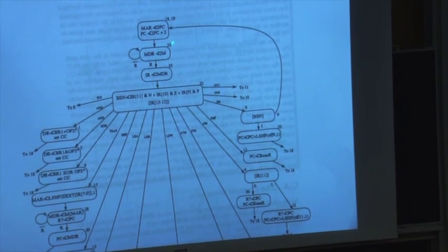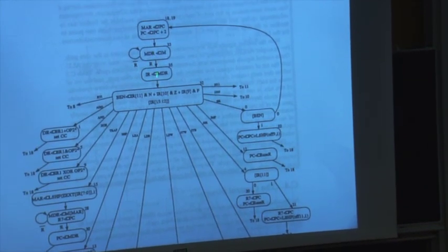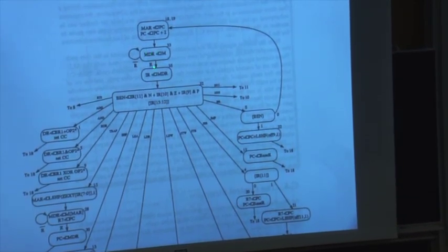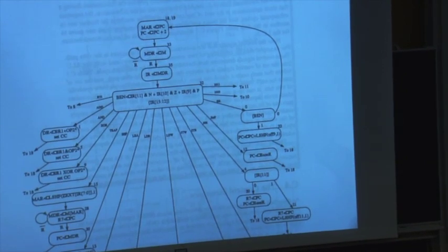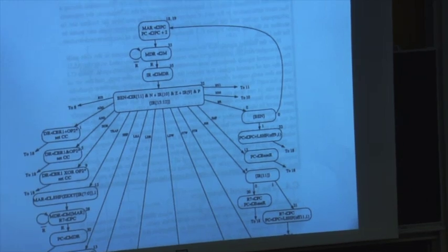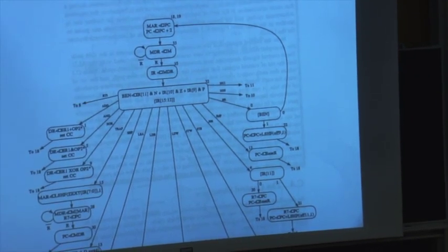Now, in the next state, state 33, the transition is conditional, right? The next state is determined by not only this current state, but also whether this R bit is set or not. Now, what is that R bit? That R bit comes from memory, and it says, is memory ready? You've already put an address into the memory, and you're reading from memory, and memory can become ready asynchronously. It could take 100 cycles.